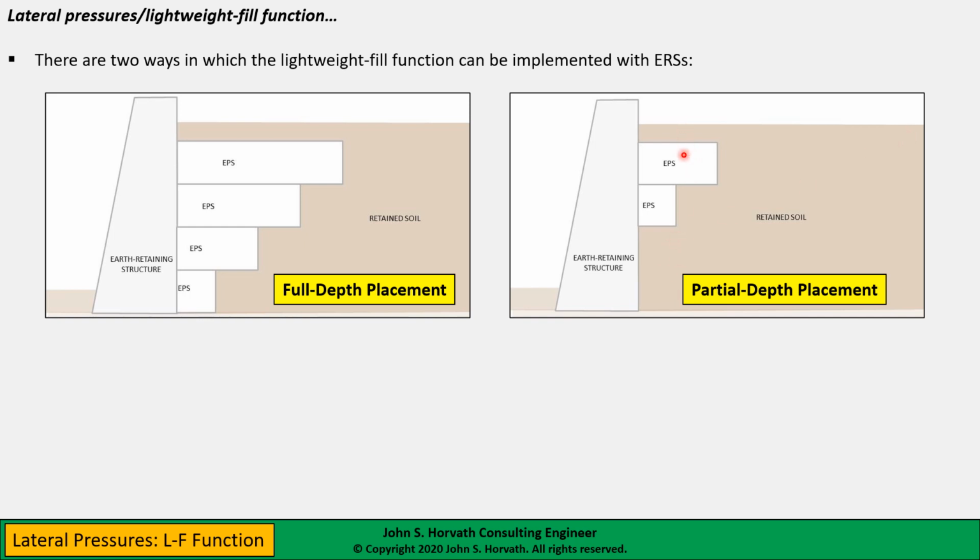So, you can't. EPS blocks have remarkable load bearing for their extraordinarily low density, but you need to be smart about it. It only works if you have the minimum thickness of pavement system up here to keep the stresses within the EPS blocks reasonable. Too much weight, in this case dead weight of soil, is going to cause excessive compression of the blocks.